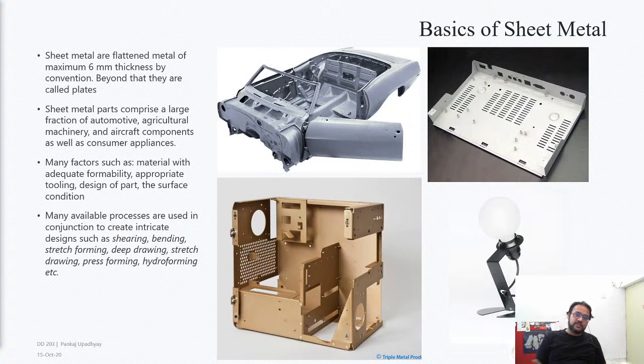So now that you've seen the versatility of sheet metal, you know what kind of operations are possible, right? For example, you could do forming operations to get these kinds of surfaces. You can get two dies that press together to give these shapes to the material. You could bend it and join it to get box shapes like these. This is probably a computer chassis, and all these computer chassis are made with different kinds of bending operations. Look at this interesting little product, quite simple, made out of a single sheet of metal. When you unfold it, it's just a single sheet, and you just fold it to get this interesting design.